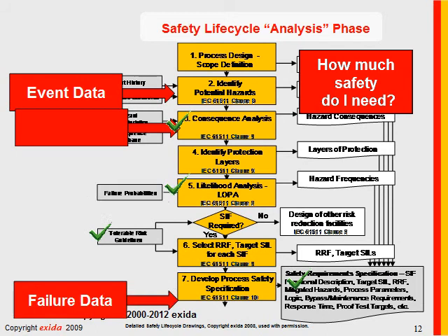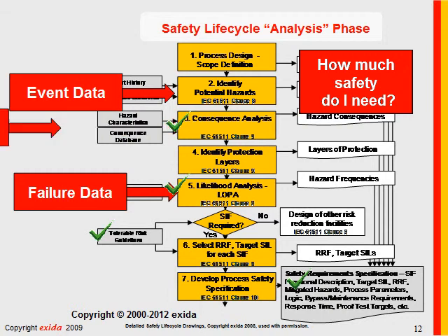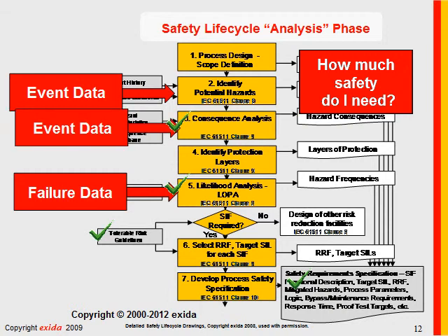And in fact, we'd like to know failure probabilities of many pieces of equipment if we're doing layer of protection analysis in order to optimize safety integrity level targets. And we certainly want event data to help us estimate consequences. So in fact, although you could certainly use industry databases, you really need to have a very good understanding of what your hazards are,